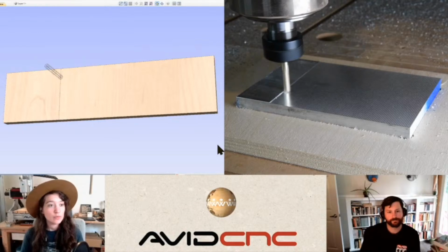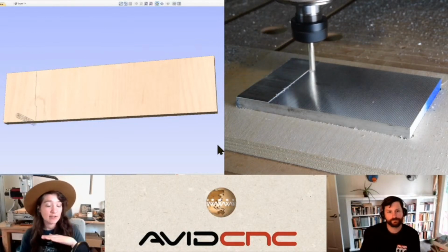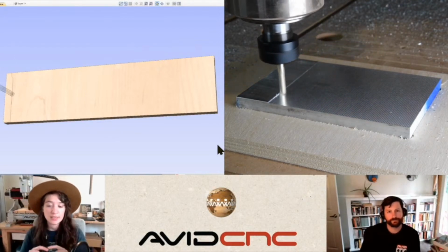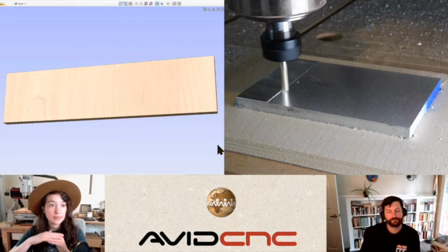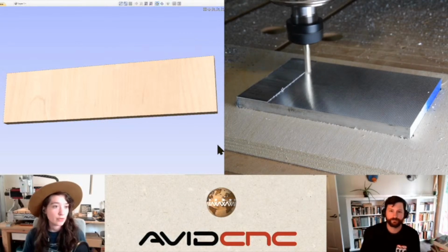And as Cory was saying before, sometimes when you place your material in your vise, it can be unlevel. So one thing that folks oftentimes do is use parallels underneath your material to make sure that they're sitting parallel and perpendicular to your spoil board or your vise.